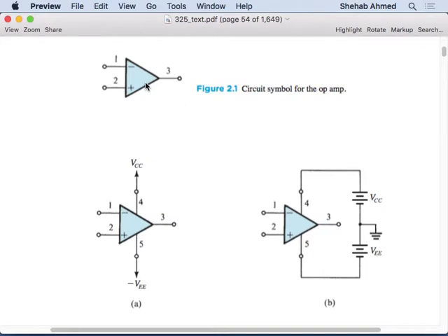Just having two nodes next to each other with different potential is a capacitance. So even parasitic capacitances will cause an op-amp to be affected by frequency. So at some point, even if it's very far away, at a very, very high frequency, it is still affected by frequency. So sometimes you need to do some frequency compensation.